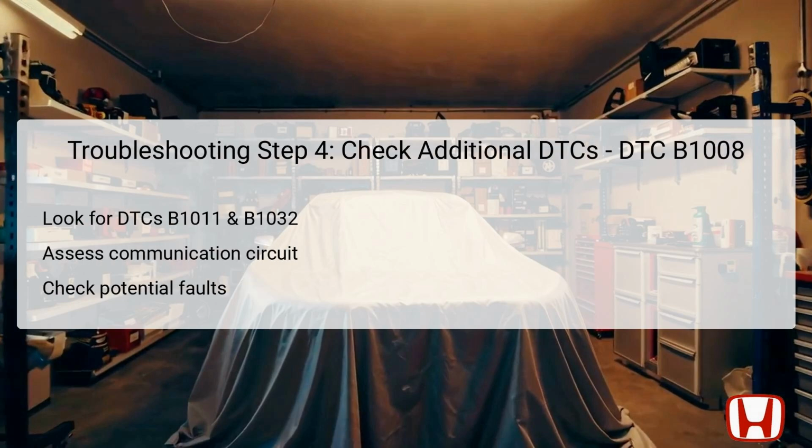The fourth troubleshooting step focuses on checking for the presence of other DTCs, specifically B1011 and B1032. If these codes are also indicated alongside B1008, it suggests a more complex issue related to communication within the system. The technician should check for an open in the communication circuit between the MICU and gauge control module.